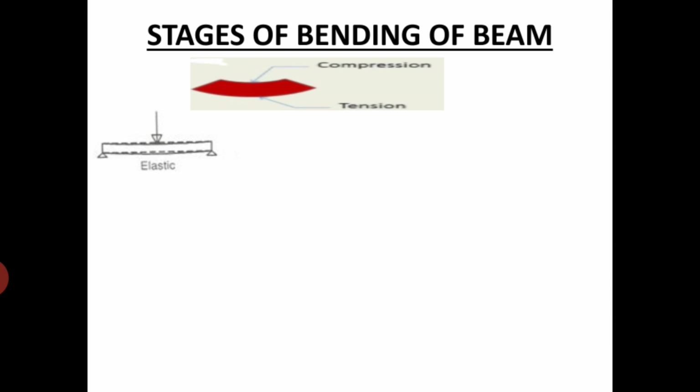We have seen the stress strain curve of steel previously, and we know what the yield stress is and where it takes place. So when the beam is subjected to incremental loading at the mid span, and the load is increasing gradually, at first the stresses at the extreme top and bottom fibers will be less than the yield stress.